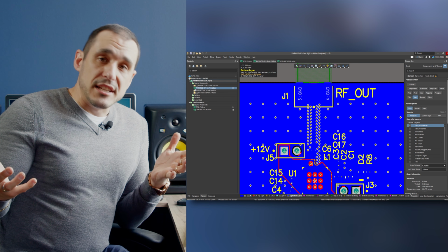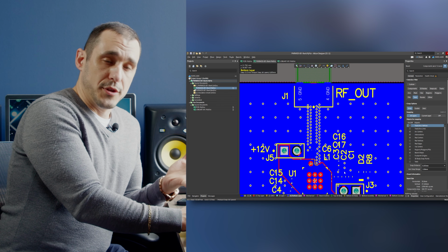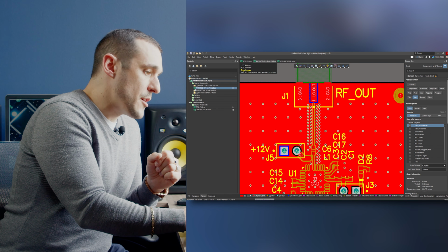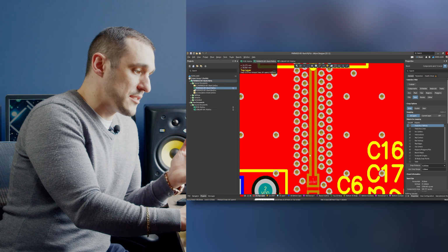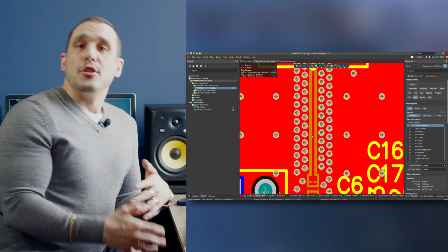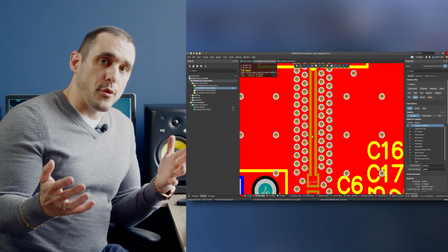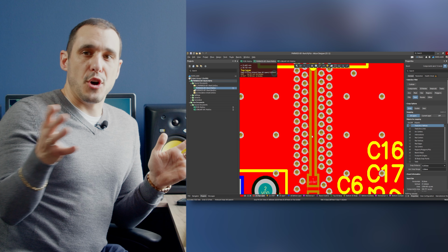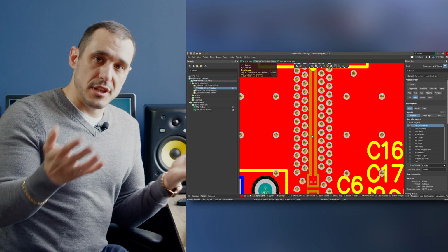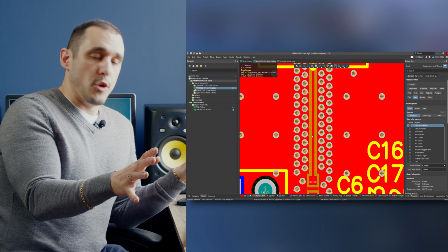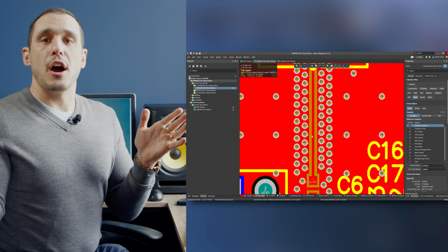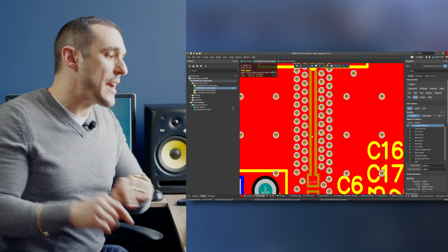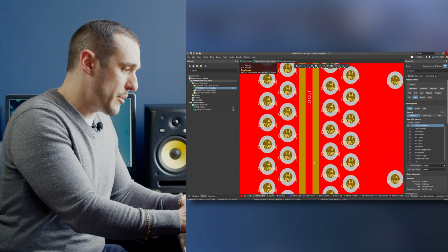So now, because we're dealing with defined impedance lines or controlled impedance lines, whether they're differential or single-ended, it is important to understand what determines the impedance of this line when you have the coplanar ground. Normally, if you look at an impedance solver or impedance calculators, they actually don't show coplanar lines. What they show are microstrips or strip lines, just really simple lines, where you don't have the coplanar ground. So it only becomes a coplanar line when you bring that ground very close to the signal line, as you can see here in the power amplifier module that we have on screen.